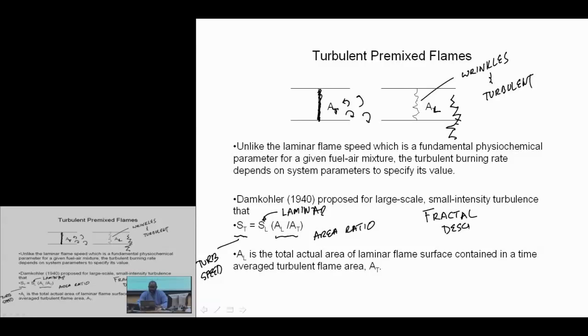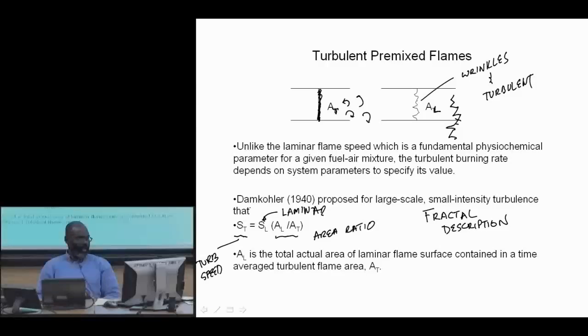If I look at this ratio being large, maybe 3 or 4, then I get an enhancement in my flame propagation speed. Okay, that's all I want to say for now, and so we will continue with more general ignition processes, spontaneous ignition, and ignition of liquid vapors. All right.